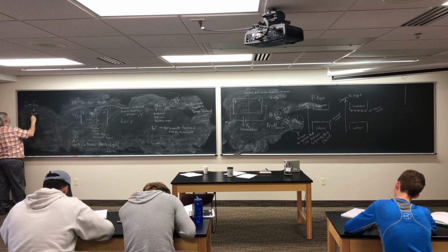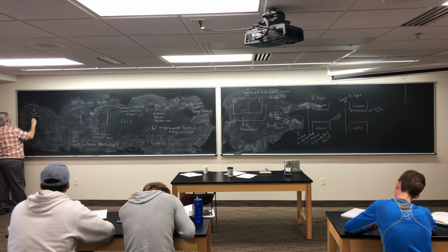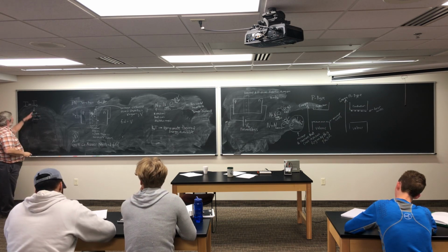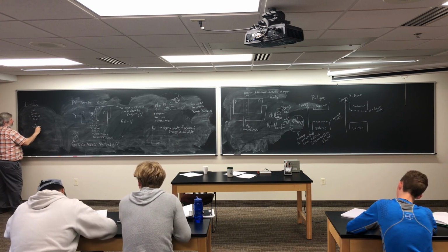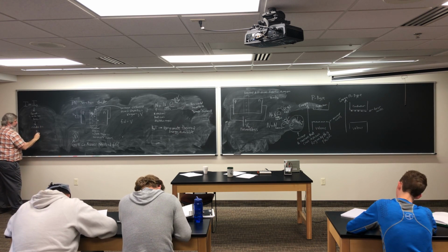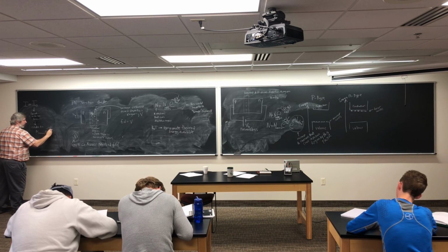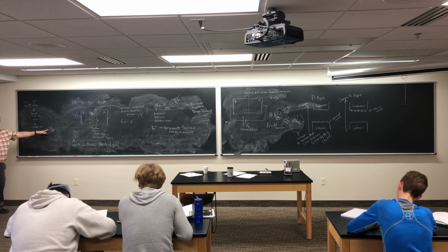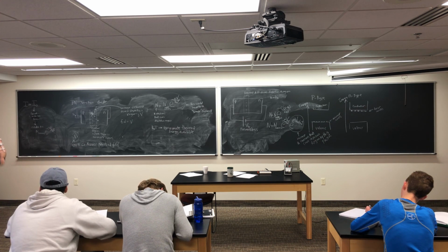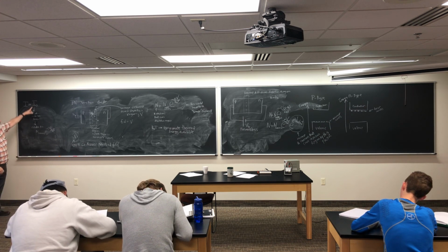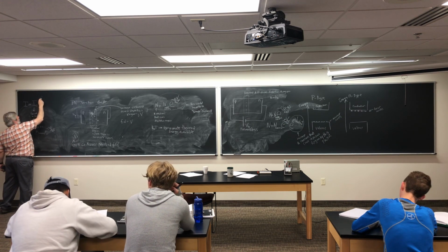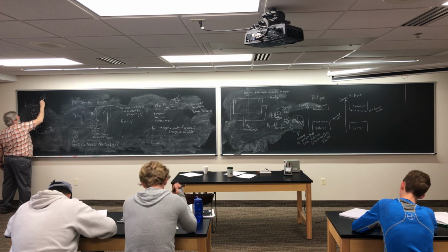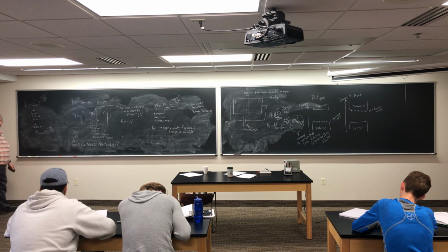Current with no bias is related to the number of carriers times e to the negative. Okay? That would be the voltage you had across that junction without putting any bias voltage on it. So that I naught's related to that. And then I'm saying we're going to increase it when we put a bias voltage on it by that factor.